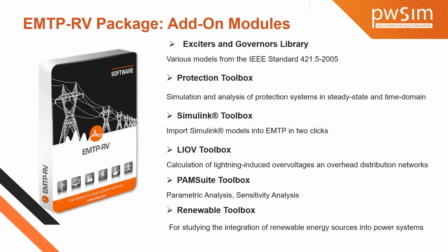Some manufacturer relays are also available, like ABB and Alstom. We can perform overcurrent protection, differential protection, distance protection, loss of field, and out of phase detection. All these things we can perform by using EMTP software.